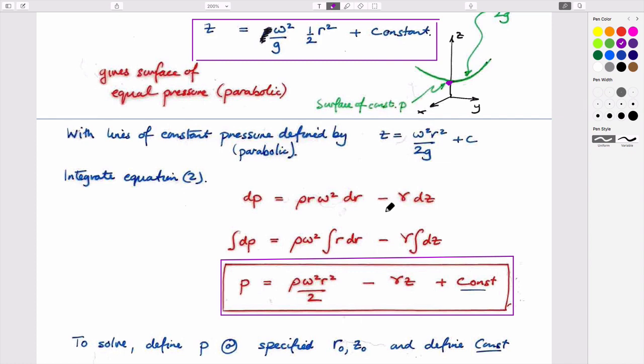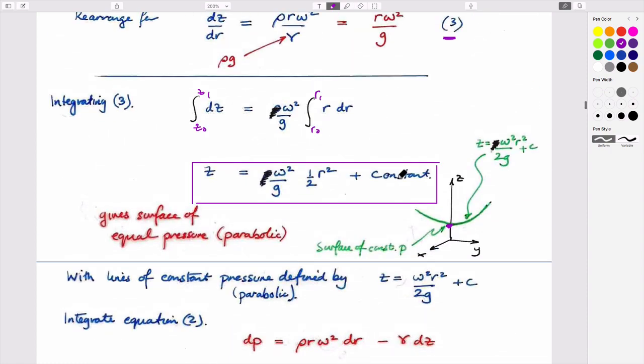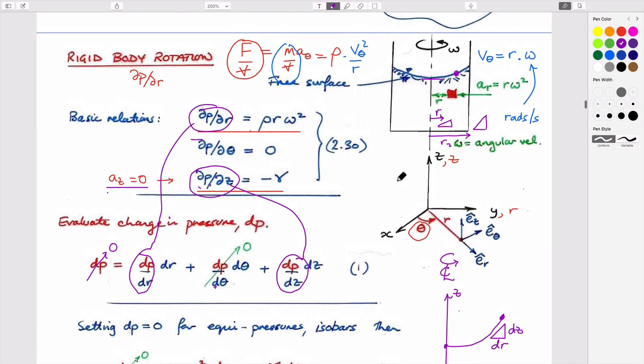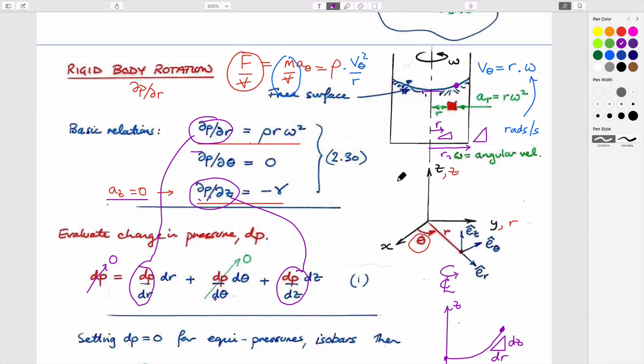And we can also get how pressures change as we go either horizontally or vertically within the system. I guess the other thing that we'd know from this is that so long as our container isn't accelerating upwards at some acceleration, then the pressure distribution we'd expect to see along the edge of this is just given by our same values before: this would be equal to dP/dz, which is the unit weight, and this is 1, right? So it'll be the same. And so the pressure distribution on the side of this container is given by that. And so we can put that to use.